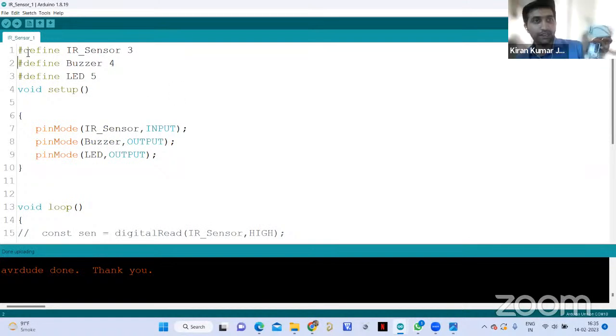So I have declared here. This is the IDE for Arduino, an editor for the Arduino software. Basically, this is how we declare the connections. You can see here I'm defining an LED on pin number 5. I have to connect the positive, the anode, to pin number 5 of the digital pins, so I'm going to connect pin number 5 over here on the board.